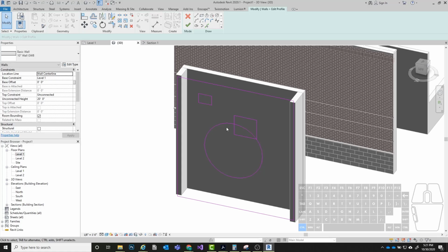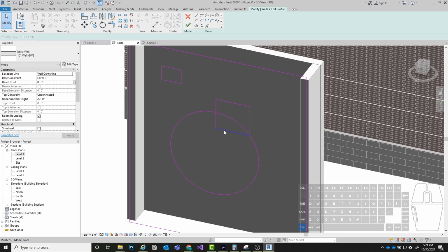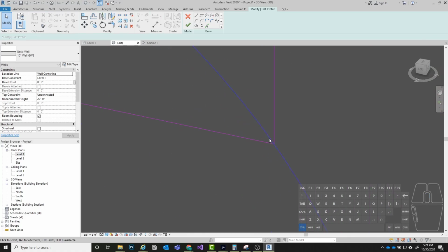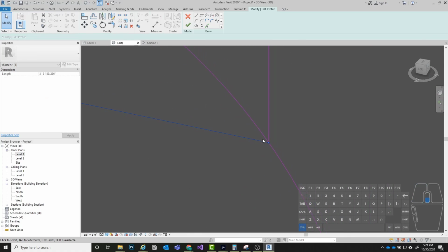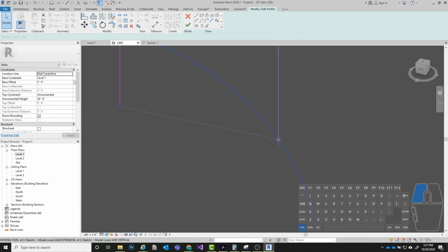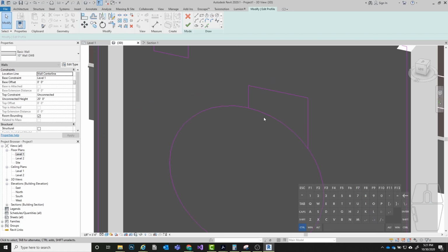If I wanted to combine two shapes, what I'd have to do is split this and trim out these portions right here. All right, so what I'd have to do is pull this. I'd have to zoom in close here, remove that line, make sure that this one is intersecting with my circle, and then drag this up to where it intersects with my circle there.